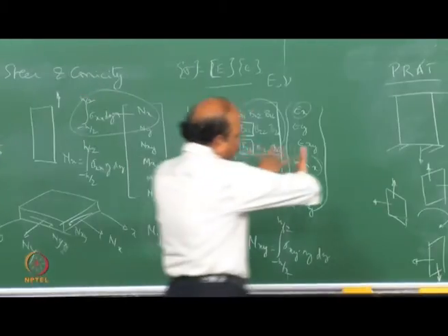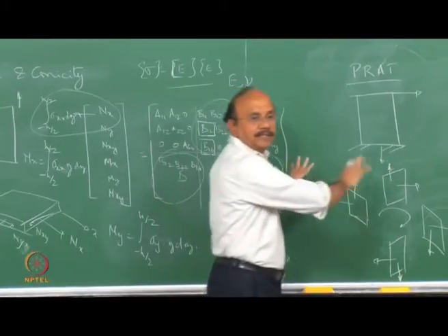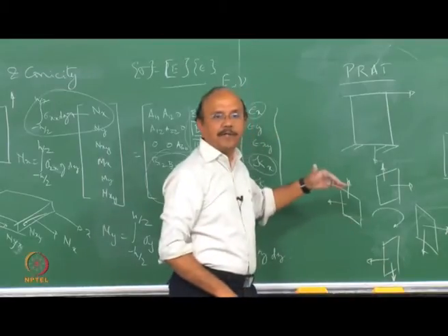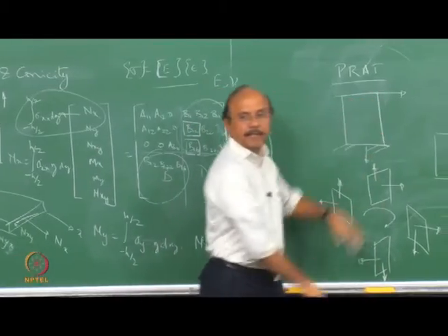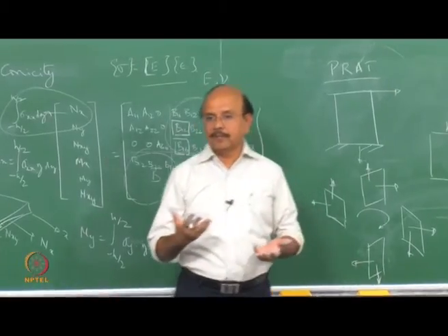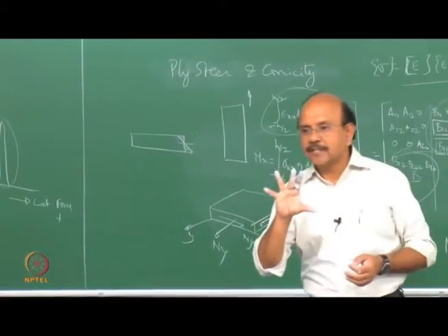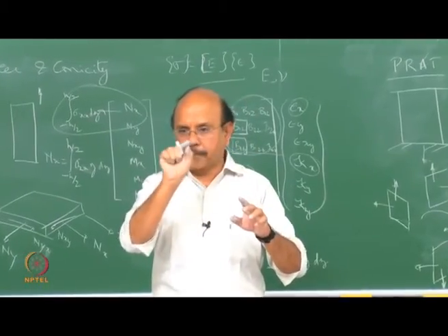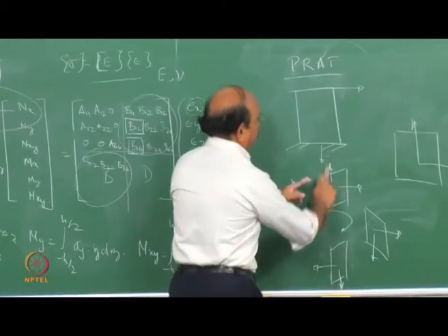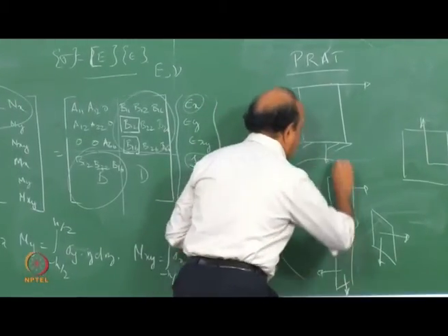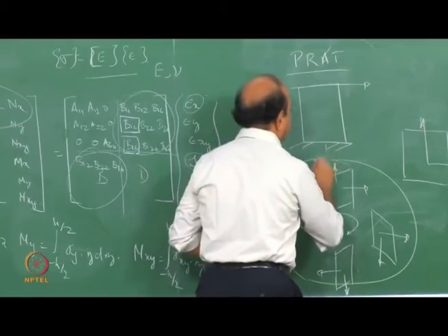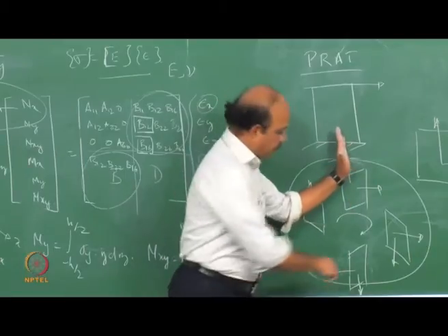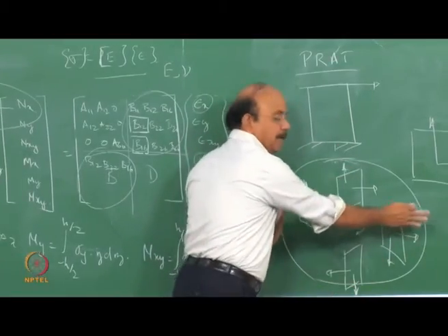At the ends, there are shear forces like that, and this is the shoulder region where there are shear forces happening like this, and at the end of the contact patch you have shear forces like that, and because of which you have coupled forces which come along with these shear forces, acting perpendicular to them.